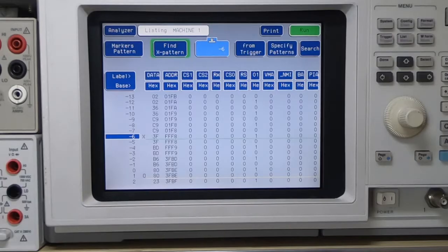Another disadvantage with inverse assemblers is that as we go through the following videos, you'll see a lot of what we're trying to capture is what we might call off-chip. It's not any of the inputs that go directly to the microprocessor. It's maybe inputs and outputs of the PIAs or the serial chip, and of course the reverse assembler would not be able to make any sense of that because it doesn't relate to operations that are on the data bus or the address bus, which is what the inverse assembler needs in order to be able to decompile the code.